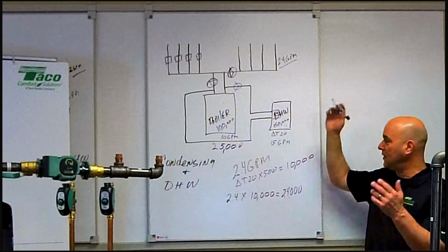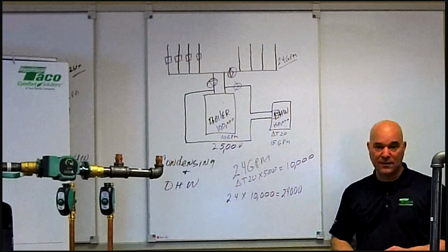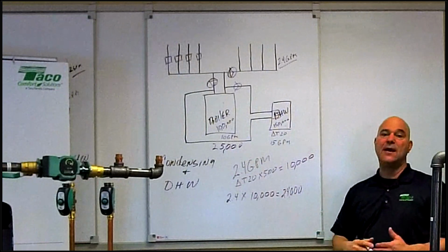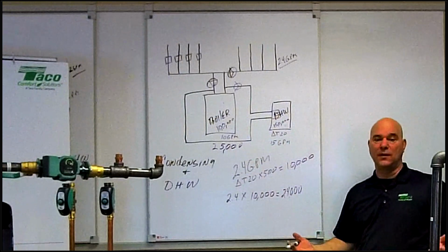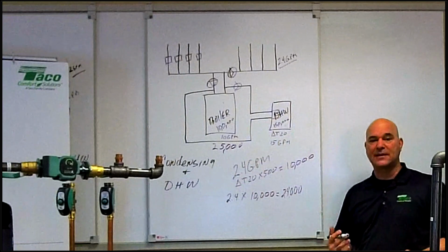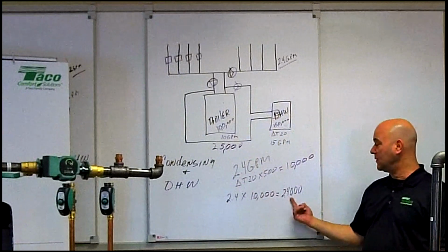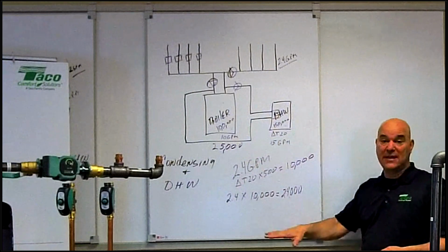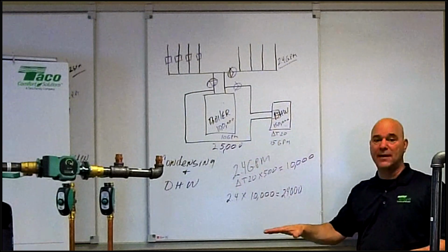If I go ahead and put in a 300,000 BTU boiler that I can only turn down to 60,000 BTU, I now have a system that's going to work like an on-off boiler. And I take the modulation factor out of it because my smallest load is 24. I can't get down there with a 60,000 BTU at my minimum input rate.